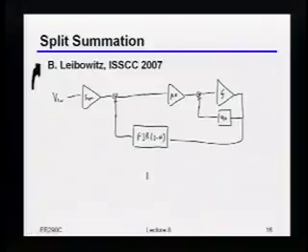So indeed, there is that issue of, well, okay, what happens when things are slightly nonlinear? Potentially that will cause an issue here. Or in fact, if you start pushing this to a high enough speed, particularly if you use something like a strong arm latch inside of that comparator, it can get pretty tough to actually hit the speed that you need. Largely that's because if you want to take a 10 millivolt input and regenerate it up to a full 1 volt of swing, that's a reasonable number of tau that you have to work with. It's about 4 or 5 tau that you need to resettle.